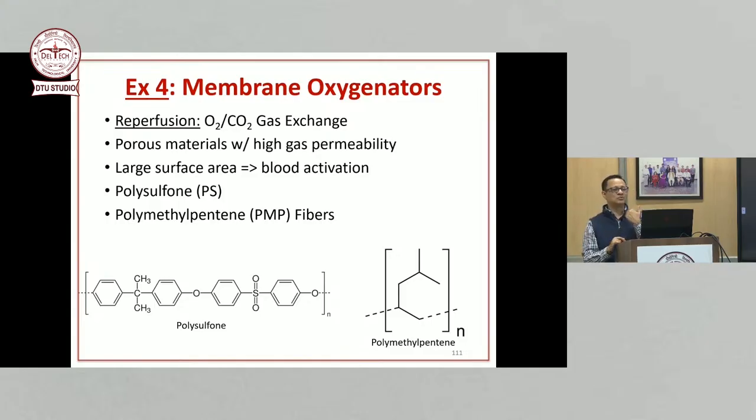It's very difficult to modify this material. Coating these oxygenators is a huge problem, because if you coat it to prevent clotting, first of all, modifying this polymethylpentene is so difficult. Second, even if you can do it, will oxygen exchange still happen properly now? Or the efficiency of oxygen exchange will go really down. Now that will be a challenge.